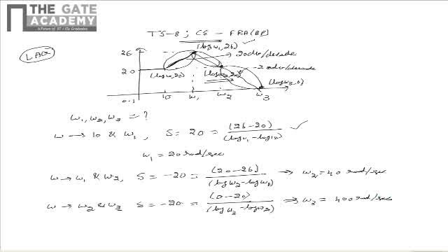So from this we see that from the given Bode plot, the angular frequencies that are marked are 20 radians per second, 40 radians per second, and 400 radians per second. Hence the correct option which gives you an idea about these angular frequencies is A.